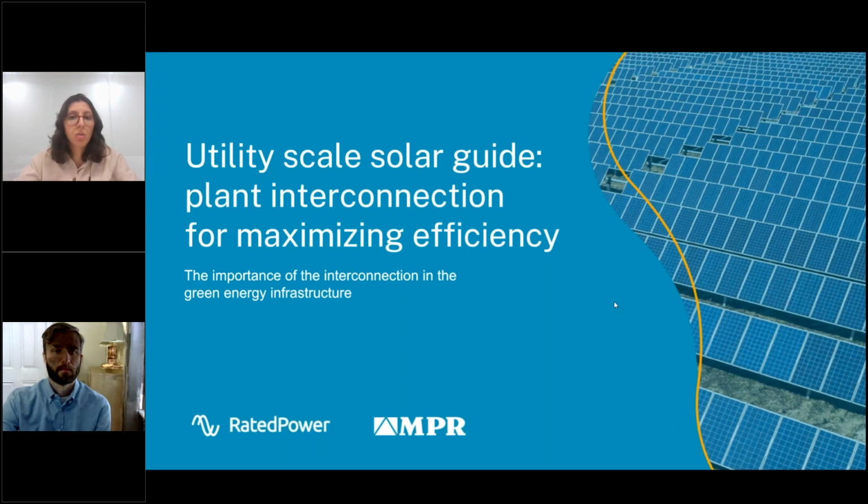That's another important point. And also we have things like batch design, where you can do multiple designs quickly over one single parameter, for example the DC-AC ratio, and based on certain steps, you can get several simulations. And then after that, we have a comparison tool in which you can compare. We also calculate the capex, and you can compare it between the simulations. Related to another question that I saw about the sites, we also offer a site creator within the software, so you can directly design or draw your site with all the elements.